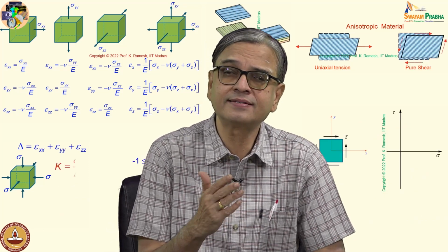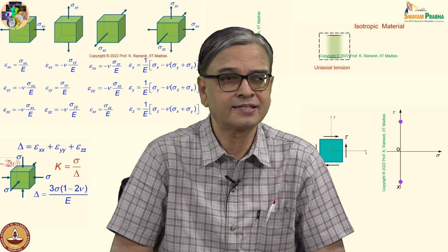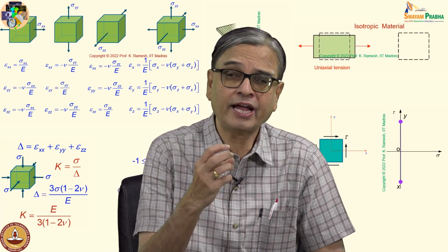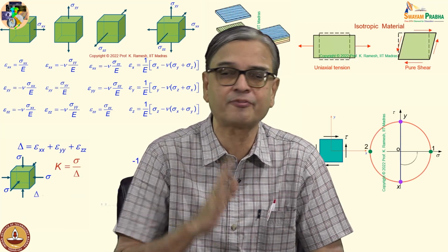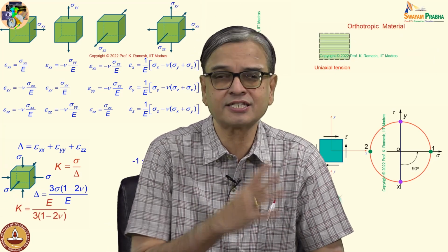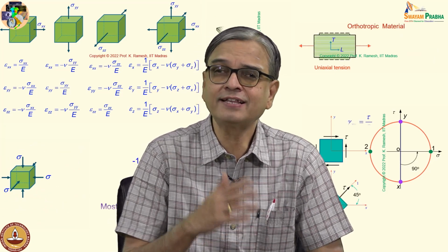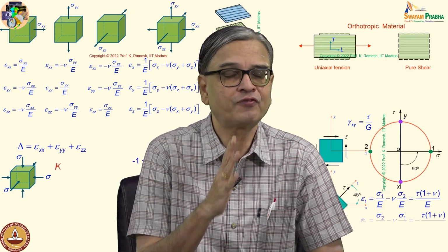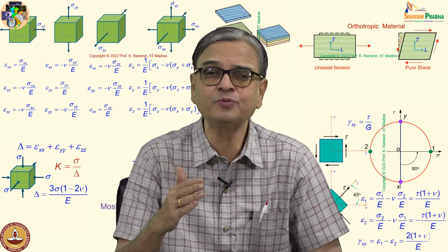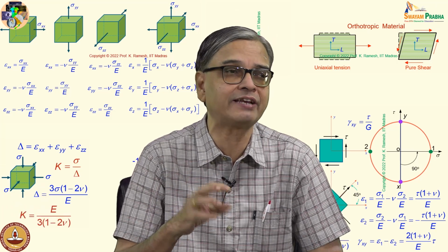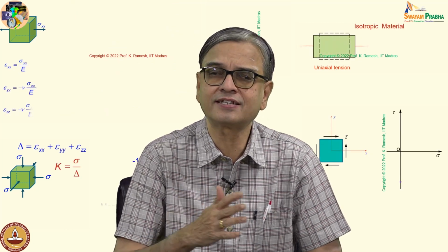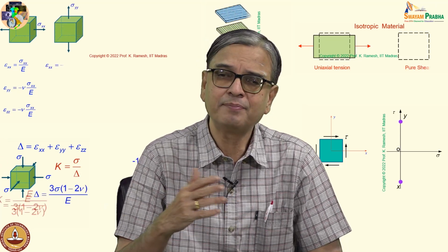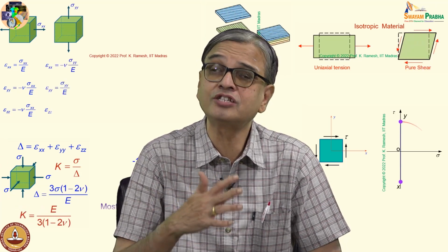And we looked at a simple tension test in the last class, and we would like to use whatever information we get in the tension test in a meaningful way in strength of materials, because that is the simplest test possible, and you try to get the maximum out of the test. So from the test you also graduate to formulate the constitutive relations. What is the relationship between stress and strain? In a simplistic manner, it is a stress-strain relationship. In a very bombastic terminology, you are talking about a constitutive relationship.